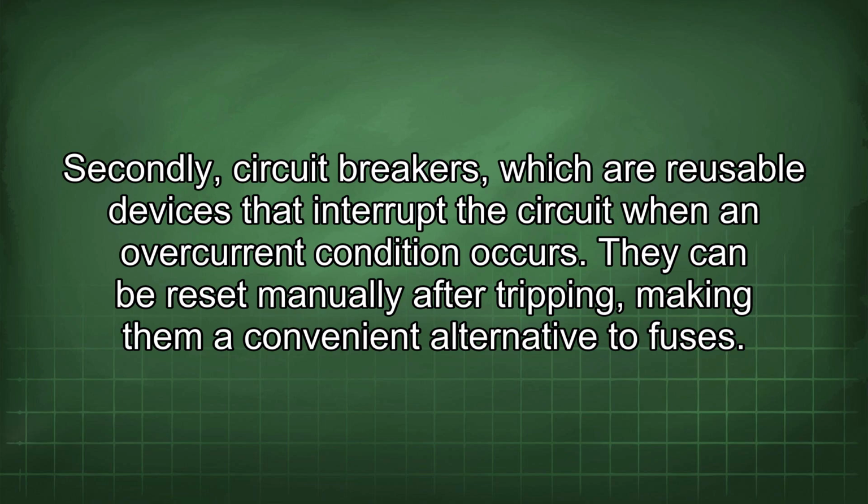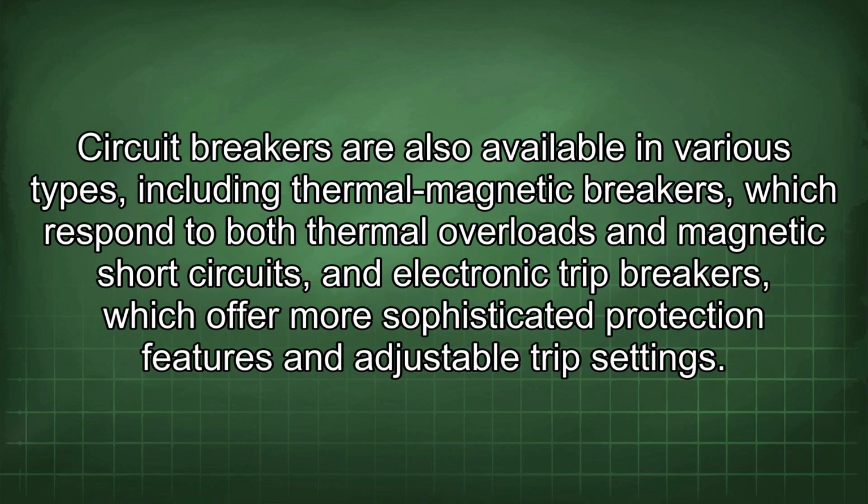They can be reset manually after tripping, making them a convenient alternative to fuses. Circuit breakers are also available in various types, including thermal magnetic breakers, which respond to both thermal overloads and magnetic short circuits, and electronic trip breakers, which offer more sophisticated protection features and adjustable trip settings.